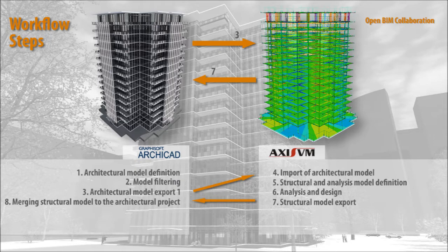By default, newly imported elements will be protected from modification, in keeping with the reference model concept. Architects may compare two view sets, one of the architectural model and the other of the imported structural model. Architects can query the profiles and materials used by the engineers and modify their project to match the imported reference model, or they can accept imported elements by using them as real ArchiCAD type elements.